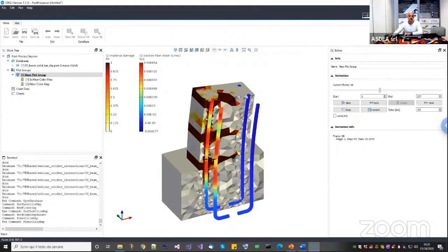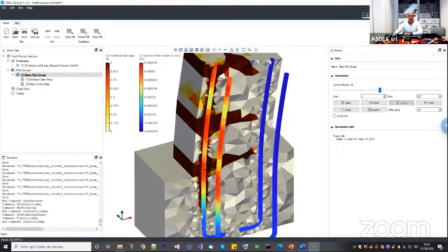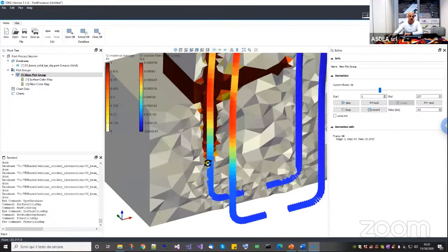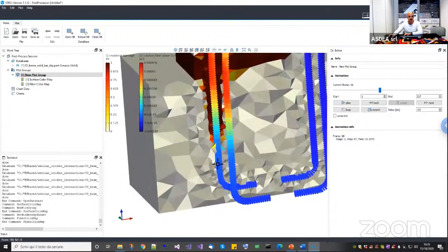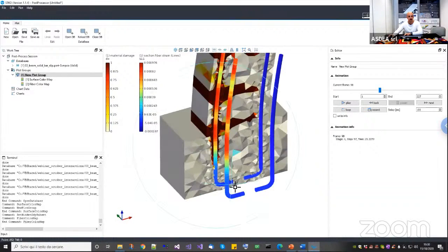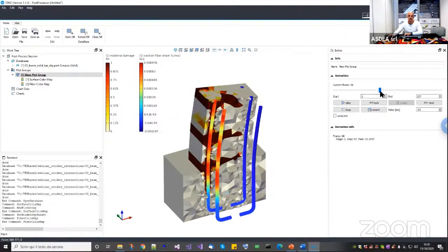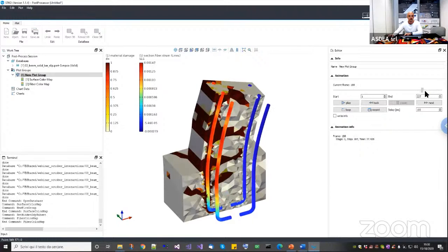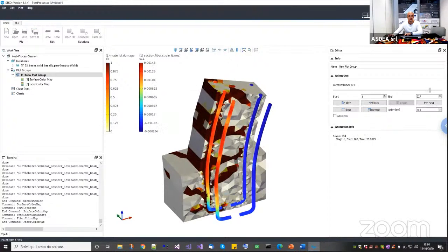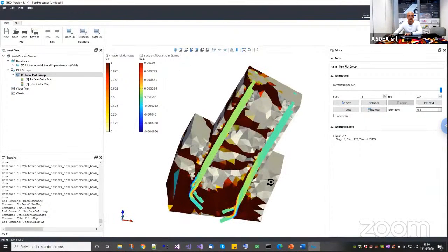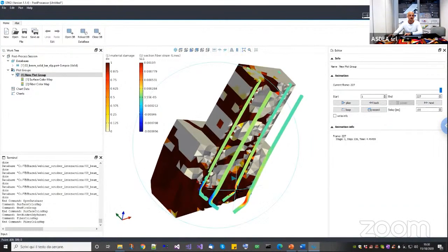Okay, and then finally, since the rebars are strongly attached to the concrete, finally it will break the concrete down here, because actually I did this model very fast, so I created this connection very close to the bottom, and so a crack will appear down here. But all of this happens because there is a perfect bond between the rebars and the concrete. Okay, so this is the final behavior. So everything is broken down here.